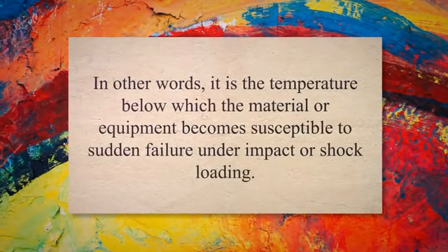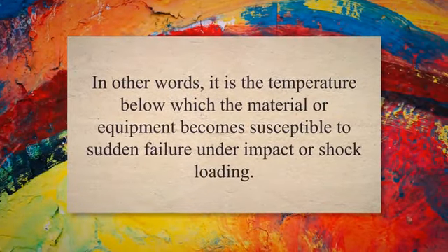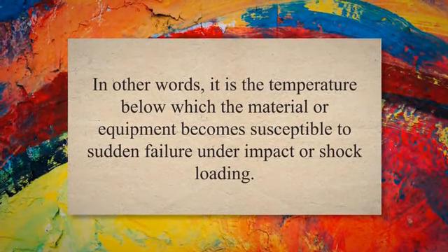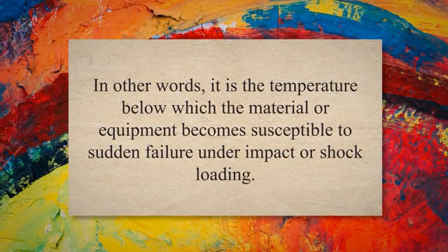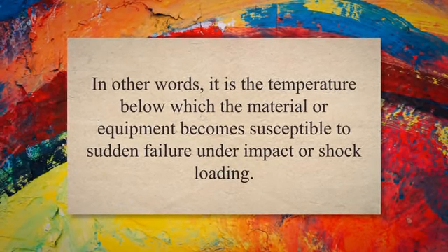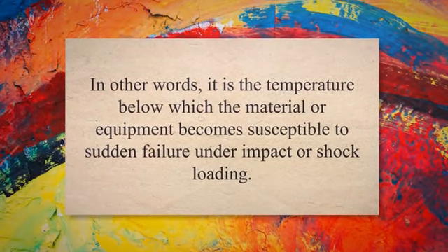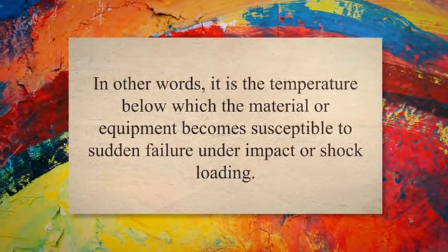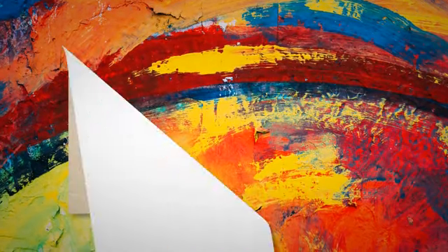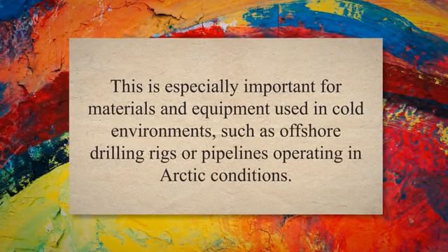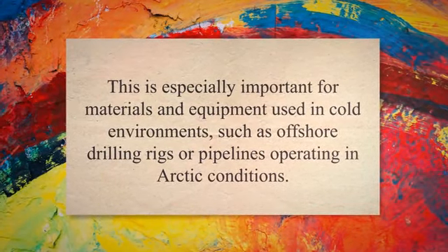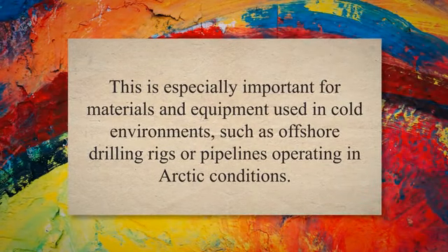MDMT, minimum design metal temperature, is related to impact testing because it is the lowest temperature at which a material or equipment can operate safely without undergoing brittle fracture due to low temperature embrittlement. In other words, it is the temperature below which the material or equipment becomes susceptible to sudden failure under impact or shock loading. To ensure that materials and equipment can withstand the MDMT, impact testing is often performed to measure their impact toughness at low temperatures.